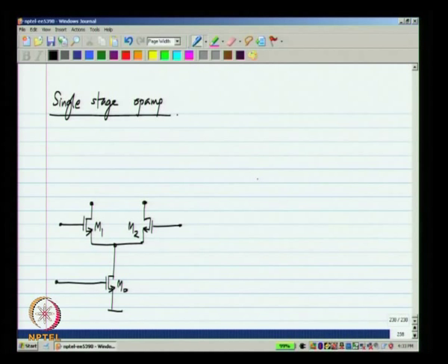As I said earlier, we can think of the cascode combination as a compound transistor with a high output resistance. So, I pass the currents of both M1 and M2. We know that if I have V bias plus Vd by 2 and V bias minus Vd by 2, I will have an incremental current Gm Vd by 2 here and Gm Vd by 2 in the upward direction in the other transistor.